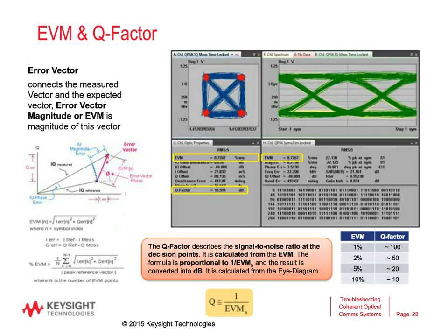The first one we look at, if we are doing this transmitter testing, is the error vector magnitude, or for those of you who are used to digital transmission or to just on-off keying, it's the Q factor, basically the eye opening. The error vector, for those of you who are not familiar with it, is basically a measurement where I compare a reference constellation point or a reference vector with a measured constellation point that I can also describe by using another vector.